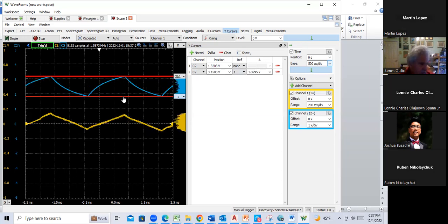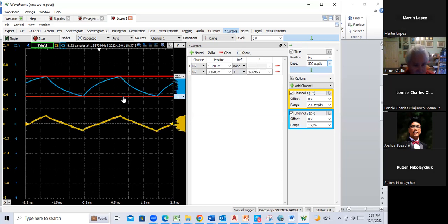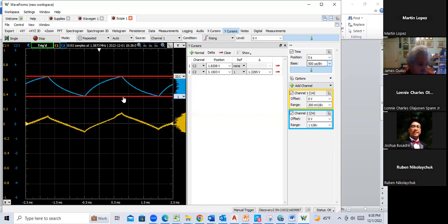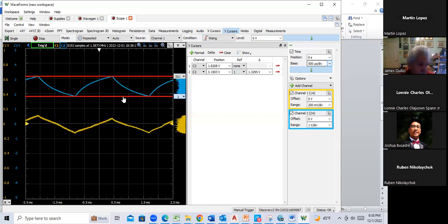Okay, so that's basically the testing you're going to do. So what I want you to do then, again, just to repeat myself, is at the end of your report, you should have the final circuit that you build with all the components. If it's different than what you simulated, maybe comment on why it's different. Maybe like you had to change RE to increase the gain to get it within your spec. But the specs have a value for minimum peak to peak voltage, so comment and show an oscilloscope display that you met that. And then comment on the gain that you met your gain spec.